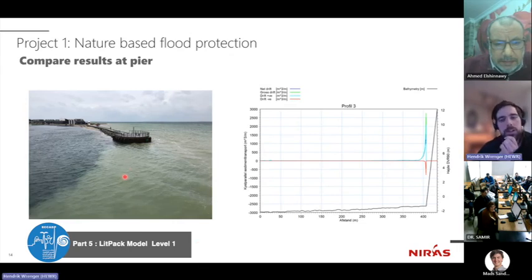And then one important component is to try to ground truth your model results. And unfortunately, in coastal engineering and sediment transport, that's often qualitative comparisons, because we can't directly measure sediment transport, right? If you set up a wave model, you might be lucky and have a wave buoy, and you get concrete measurements of the significant wave height, for example. Then you have a quantitative measurement which you can compare against. With the sediment transport, that's a bit different.